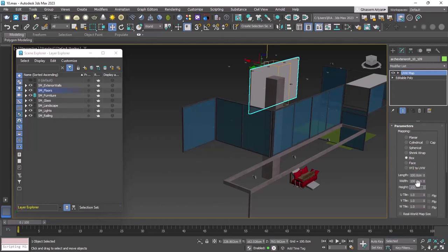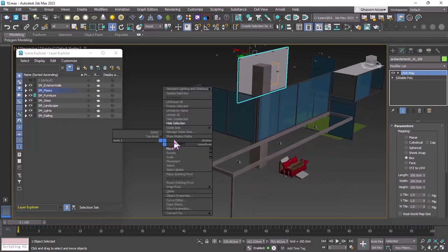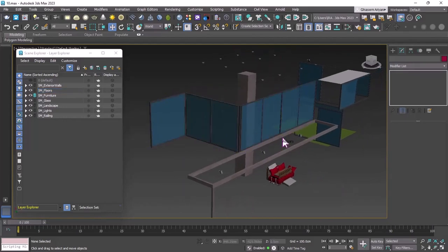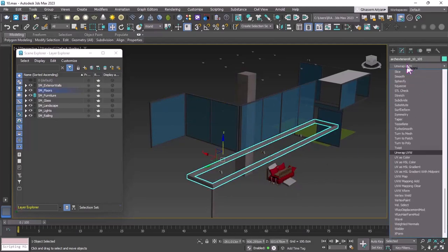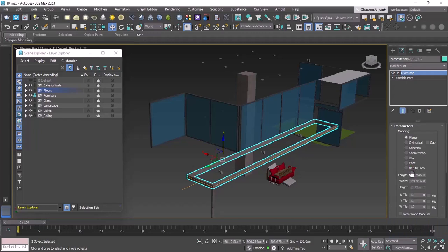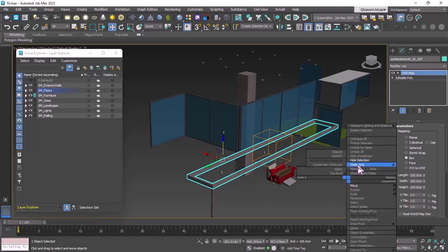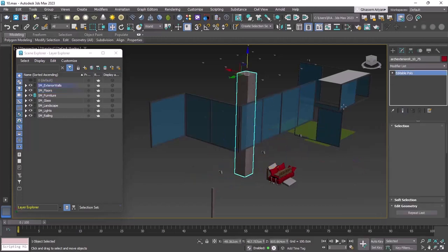Here, let me tell you something, which I will talk about deeply in animation, but when you have some doors or windows in Unreal, which maybe you want to animate them, it's better to separate them and have them in another layer, like furniture, to be able to control their pivot there, to have animation. Except for this, it will be really hard, as I told you before.